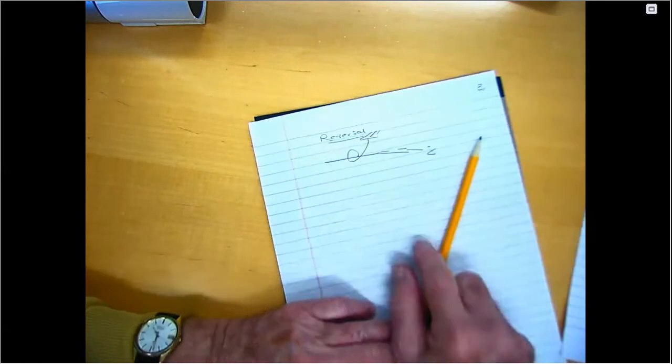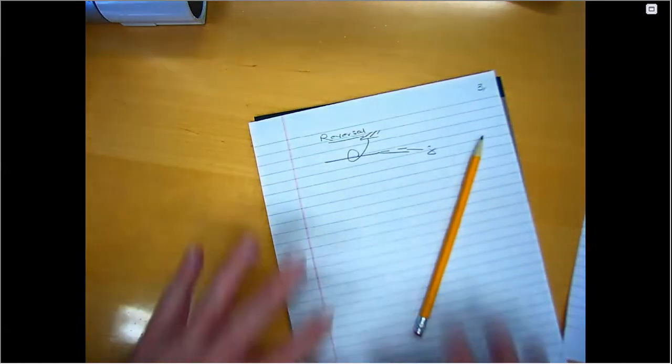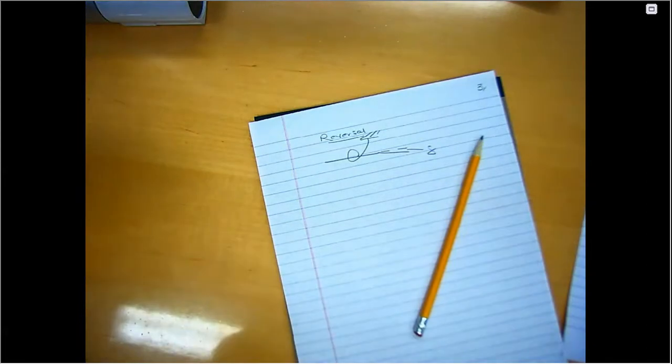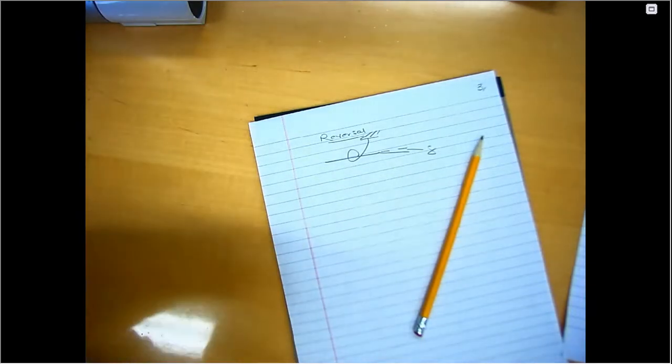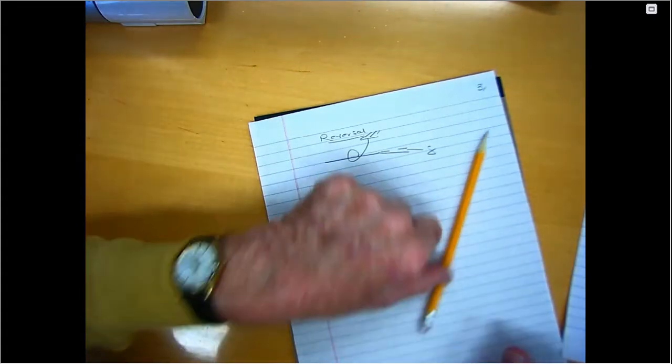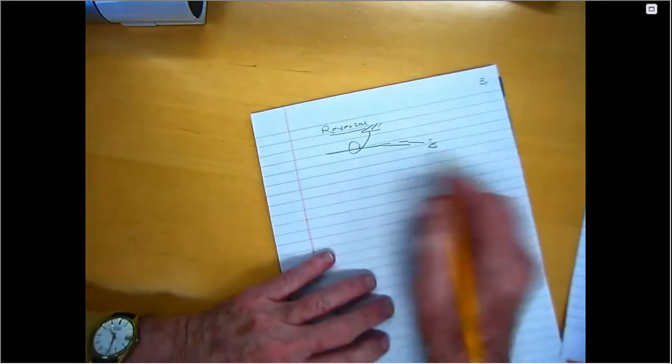Another more elaborate form is if I have a real airplane wing, we'll talk about a more realistic model in a moment, maybe toward the end of this class. If I have a wing with two control surfaces, I may want to roll the aircraft, which means I rotate this one down, this one up, right? And so you can have rolling reversal, where you have two control surfaces in opposite wings, and they act anti-symmetrically. But here we're going to keep it simple, right? We're just going to think of one wing or one airfoil.